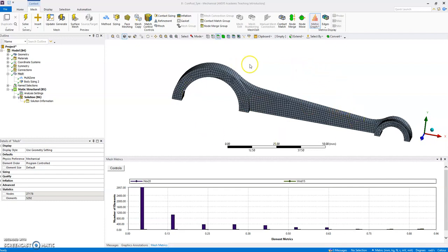So depending at which stage in the cycle the piston or the conrod is in, the loading differs. At some point, just after the explosion, we very likely are going to be in compression, okay? Beginning of the compression phase, the piston pushes on the ring, pushing on the pin, pushes on the conrod, goes down, and there will be some resistance, at least at the beginning, from the journal in the crankshaft.